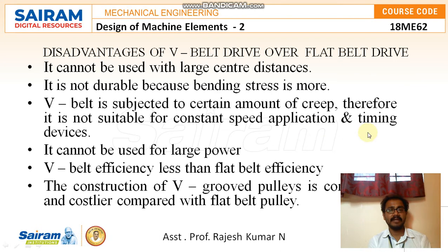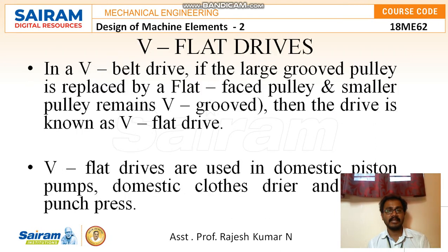And it has some disadvantages also. What are the disadvantages? It cannot be used with large center distances, and it is not durable because the bending stress is more, and the V belt is subject to a certain amount of creep. Therefore it is not suitable for constant speed applications and timing devices, and it cannot be used for larger power, and the V belt efficiency is lesser than the flat belt efficiency. The construction of the V grooved pulleys is complicated and costlier compared with the flat belt pulley. Okay, it is a little expensive.